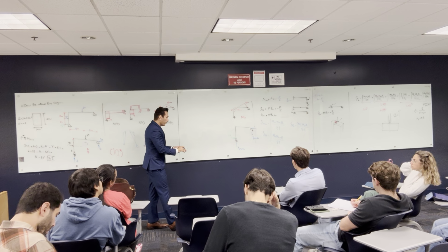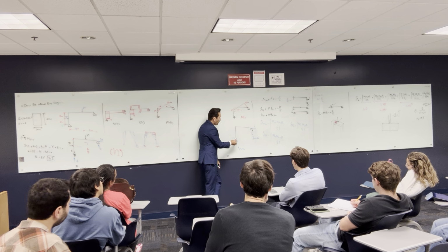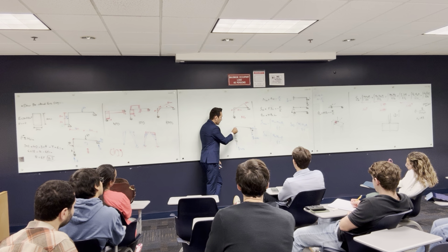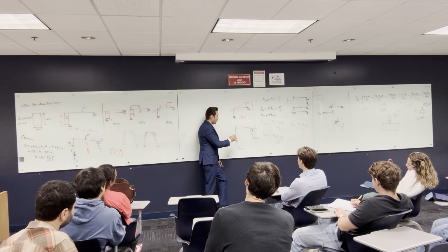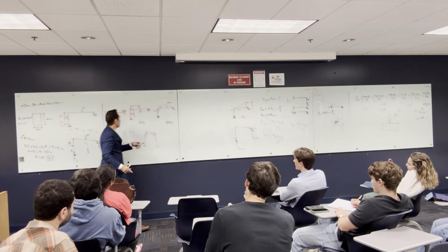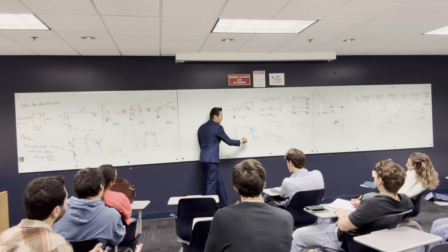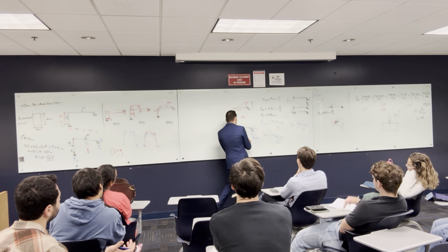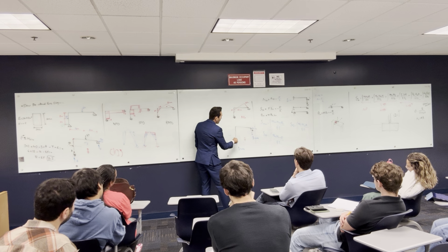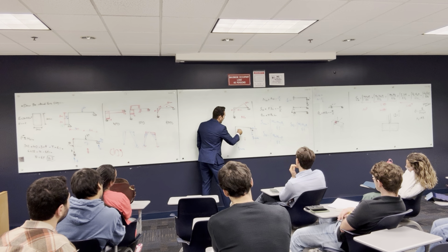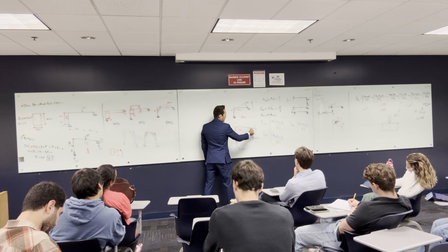You can draw the bending moments. Can you tell me how I can get the bending moment of this frame? What is the moment here? 0. How about the moment here? 1 times 4, sorry. Yeah, this one is 4. Is it positive or negative? Set yourself here, inside, and this load is going to make a bending moment that way, so it's going to be negative. We put the negative inside, and this is going to be 4 ton meter.